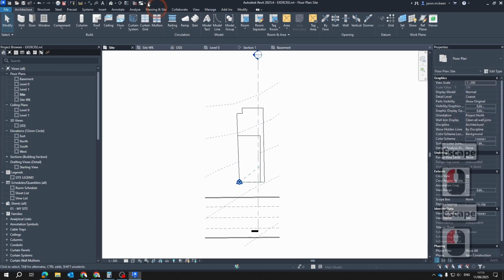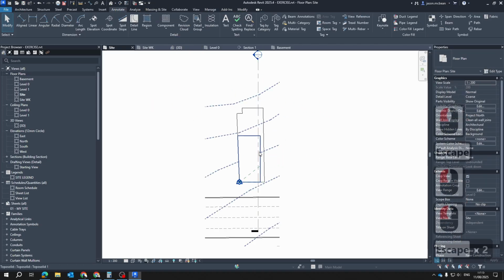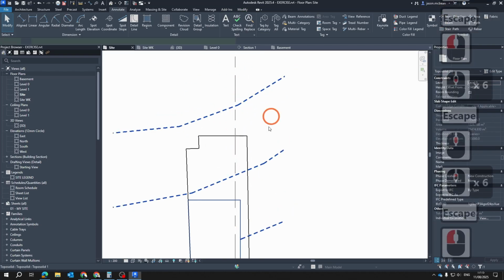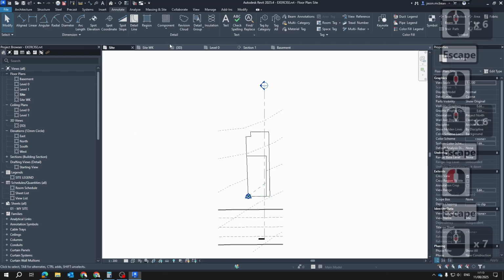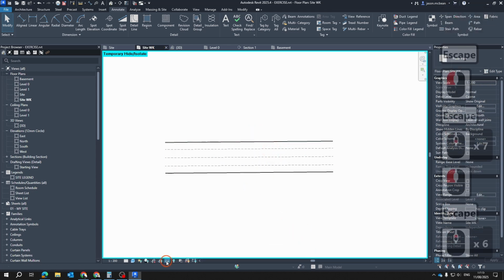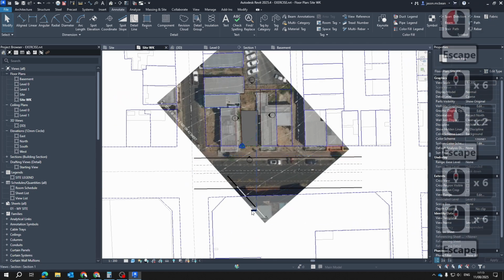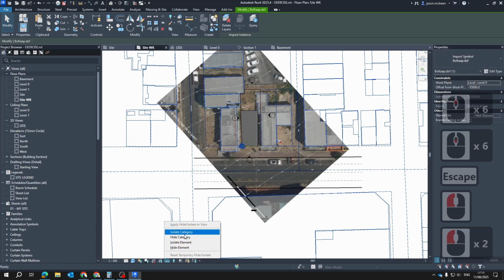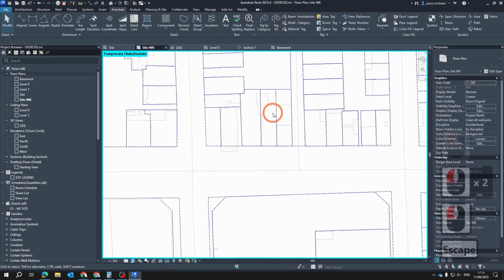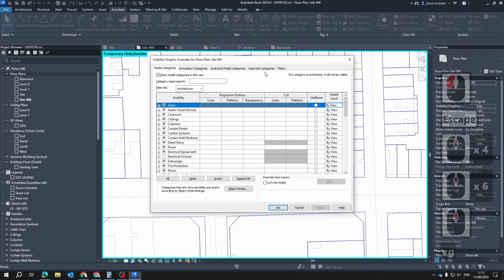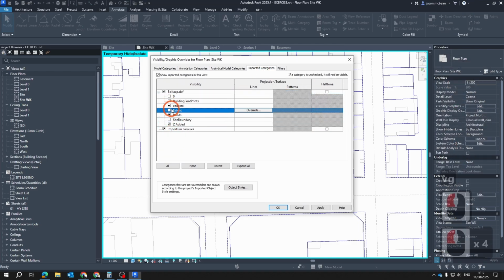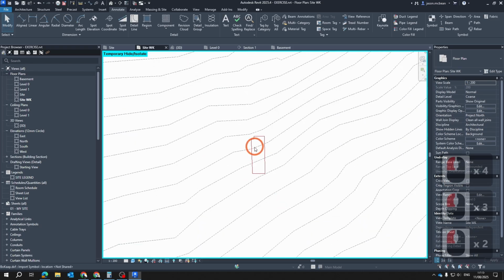so I'm going to go to Annotate. It doesn't matter where this goes through, but I'm going to use this now. So I'm going to go back to site working. I'll explain why. Reset temporary hide, and I'm going to isolate just this object. Isolate element. I'm going to go to VG, import graphics. I'm not going to switch off everything. I'm just going to show Z and my site boundary. Press apply, press OK. Good.